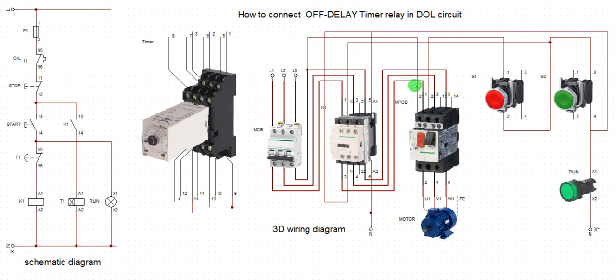So let's incorporate this into the wiring of this DOL. Remember, the entire wiring here is the same thing I have here. Here is the schematic. Then this is the wiring representation. Okay, all right. So let's do that now. Now the same thing. Remember, I break up a circuit before the coil for me to insert the contact. Now the same way, look at my coil. This is A1. So I break up this place. Okay, look at joint here. So all you need to do is to, sorry, take it away. All you need to do is to break up here. Before this one coming to coil, I have to feed the off delay timer.